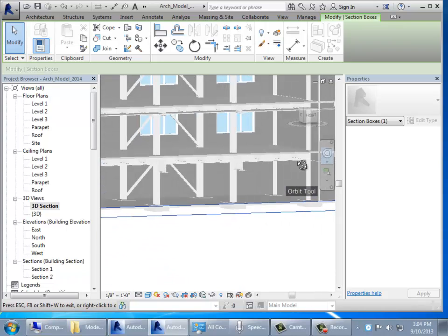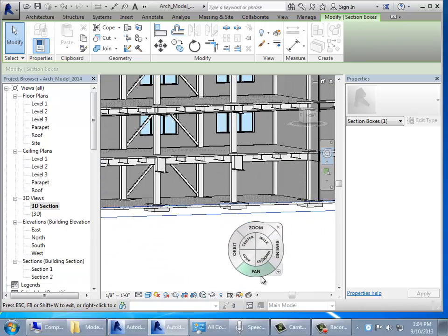But the important thing about this is that by linking things together, you can have several different people all working on different pieces and they're all staying in coordination with each other. Now, linking actually does work two ways. I'll show you how to set up links, because you'll want to do this in your model too. You can link the structure into the architecture and the architecture to the structure. You can go both ways, because ultimately, everyone wants to be able to see the other pieces that they're not seeing.